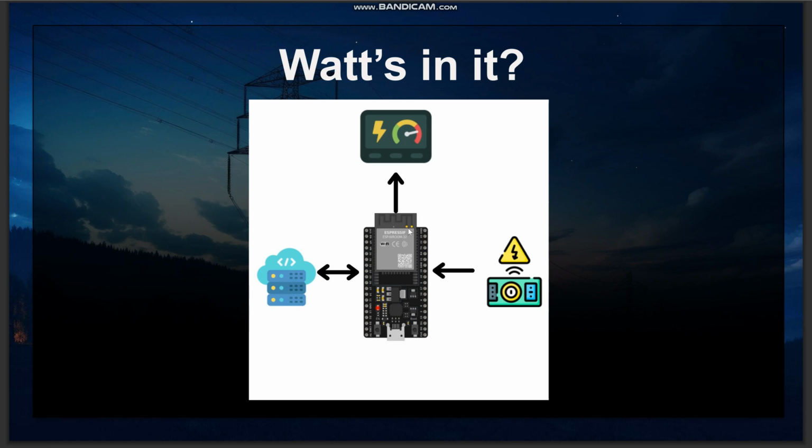So we received the data of both current and voltage from the sensors, and we just transmitted the data to the cloud using the onboard Wi-Fi in ESP32. And we also built a dashboard to process the data received from the sensor and show the real-time alerts and any insightful data from which the customer or any user can take actions.